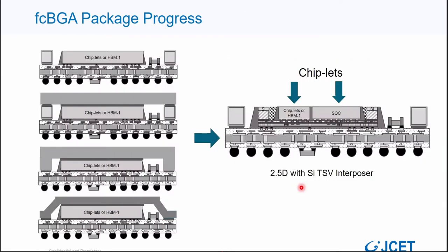So from the heterogeneous integration point of view, high-end application mostly focuses on FCPGA packaging. For FCPGA packaging, the left side shows four kinds of basic structure. If it is only one SoC chip, it is either with a stiffener ring, or a stiffener ring plus spreader two-piece structure, or this forged die lid for better warpage control and heat sink control.